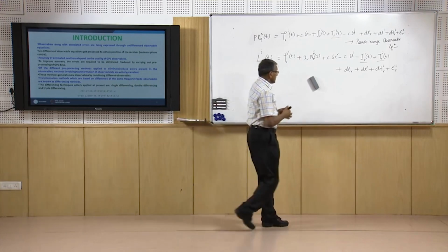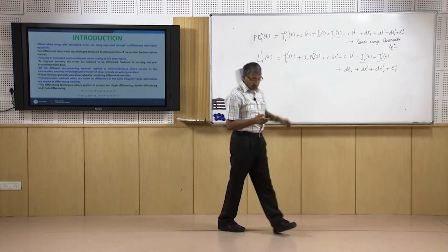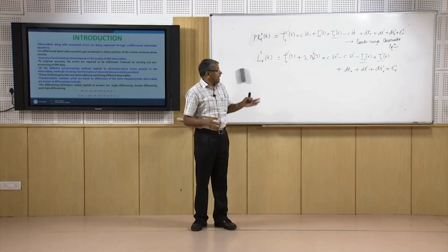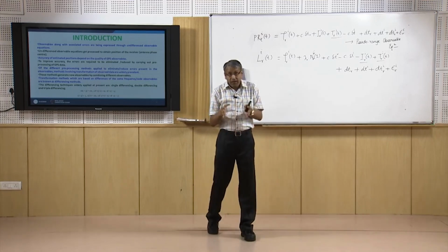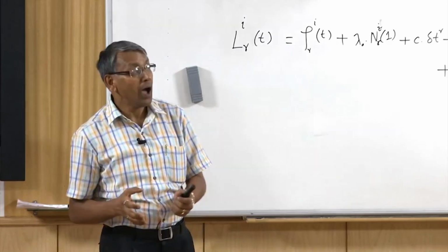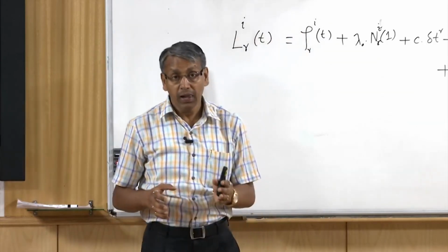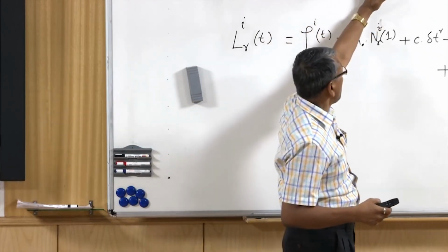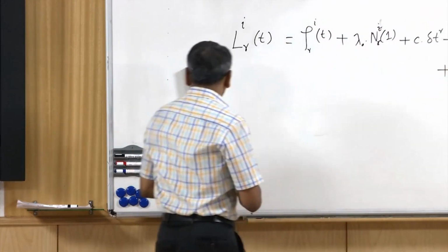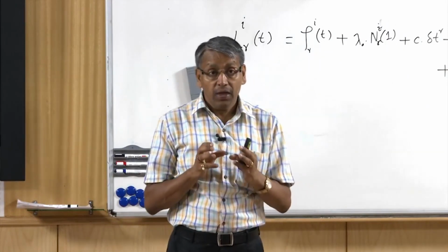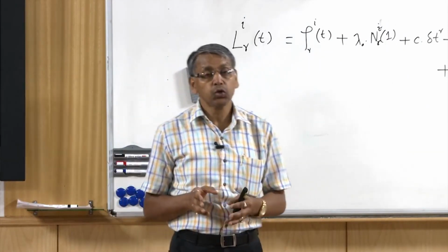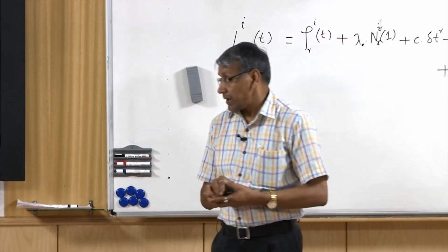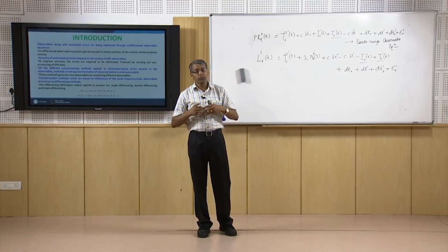Now we process these observable equations to determine the position of the receiver. The quality of the position will depend upon the quality of these observable equations. That means these observable equations should be free from all these errors. So to make these observables free from errors, we need to pre-process the GPS data, and to pre-process the GPS data we adopt many methods.